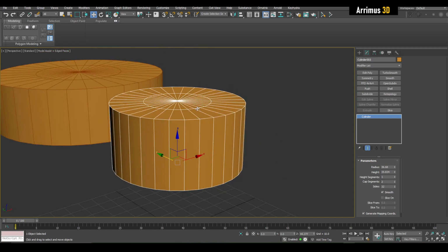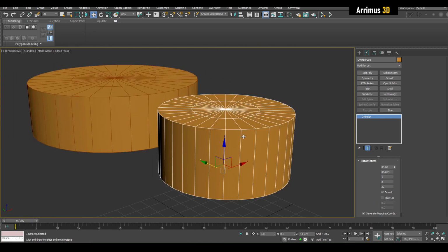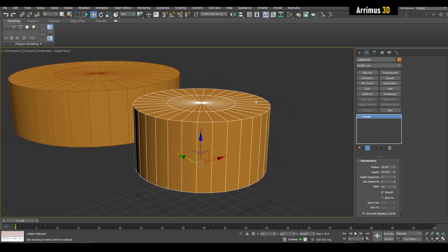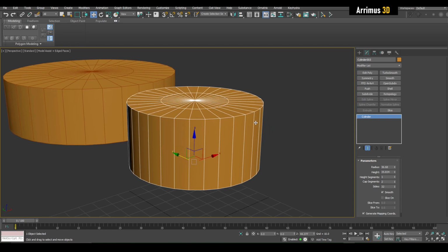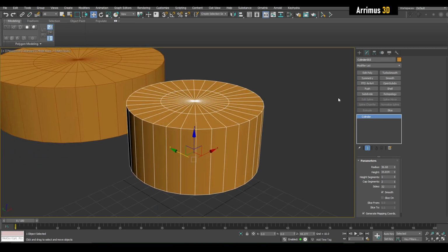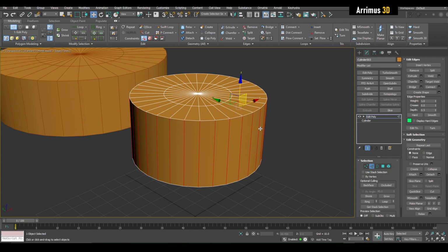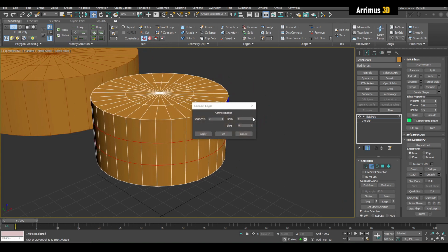And so when we create the blockout, guys, you don't want to spend too much time on one part. You also don't want to make it too detailed. But you do want to have enough detail to describe what you're doing so it becomes much easier to edit later on. So what I want to do here is create a quick object that represents the seat where the driver will sit, and perhaps some windows as well. So I'm going to apply edit poly, and I'm going to select an edge and ring and connect to and pinch.